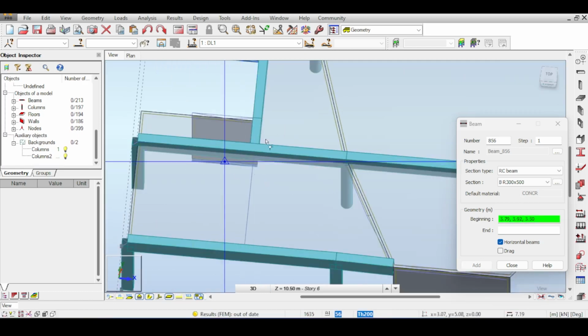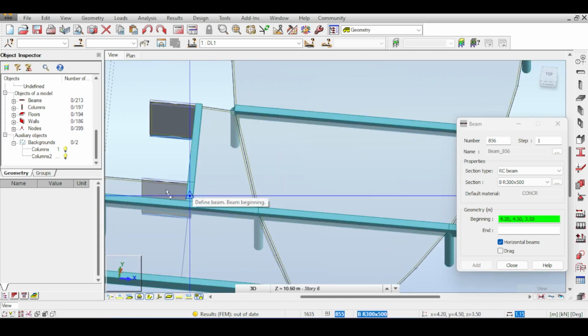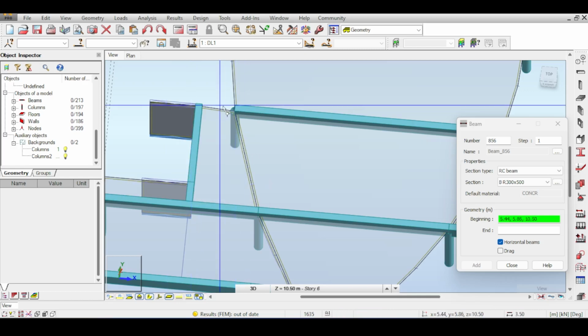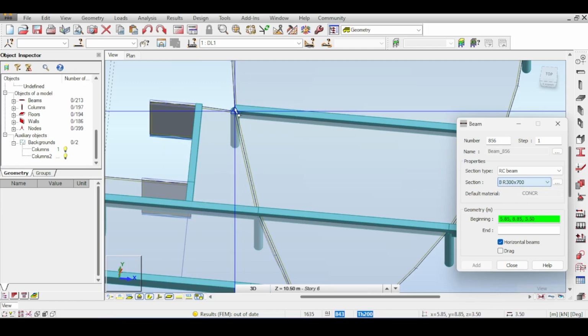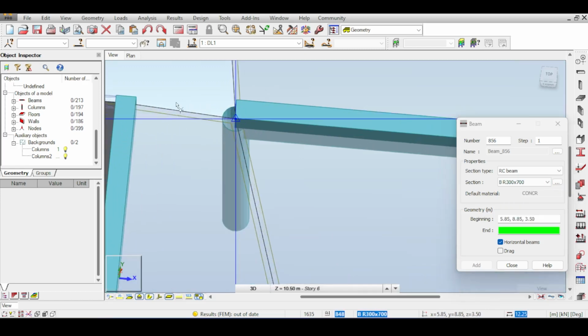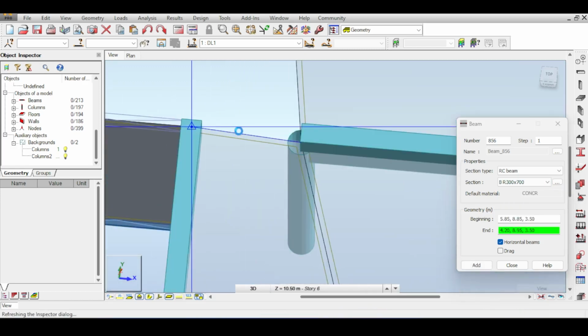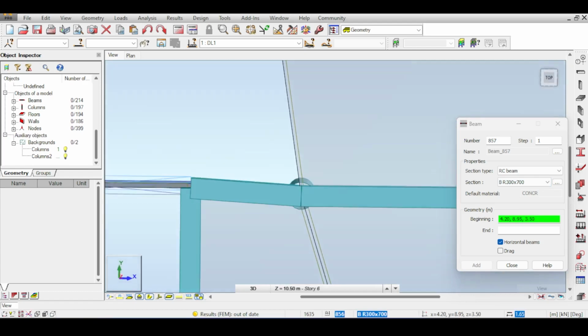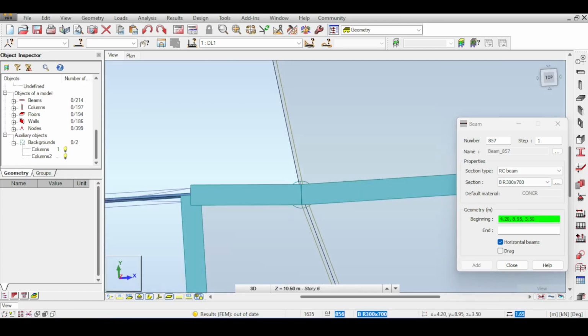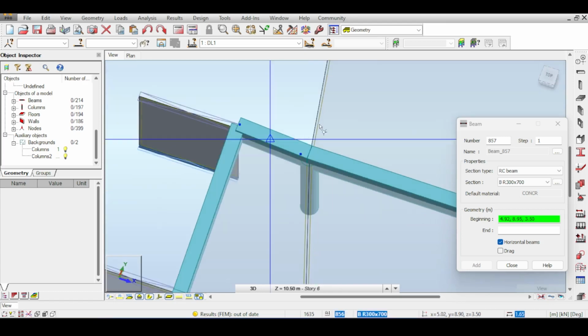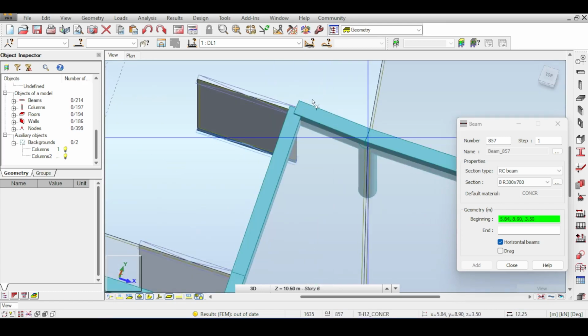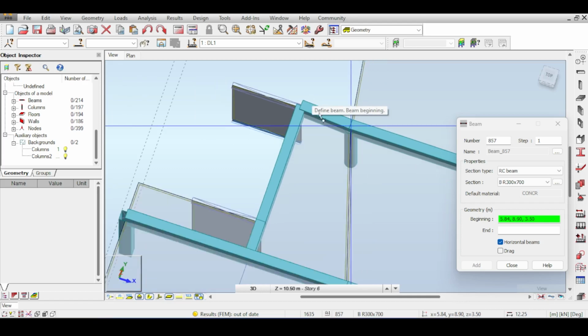This here, this is one of the danger zones. Do I have to carry it like this? I'm not really convinced I need a main beam here, because a slab is available to carry itself, and it's going to be carried by those two beams. Like this beam is going to extend to the wall, of course. Like this is going to extend to here. Wait, why did it break like this? Wait, what? Oh, okay, no, this is not dangerous, because the wall has a thickness, so of course the beam is going to be carried by the wall. I'm kind of annoyed.